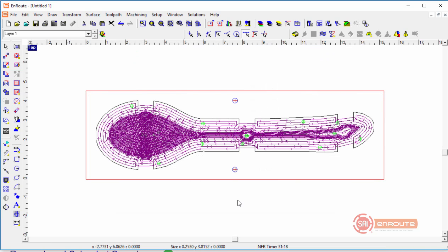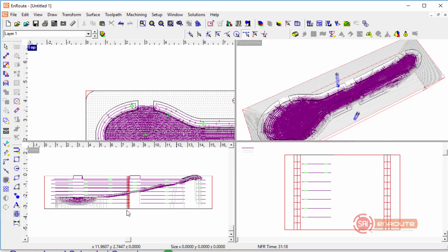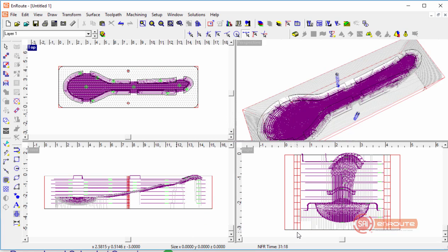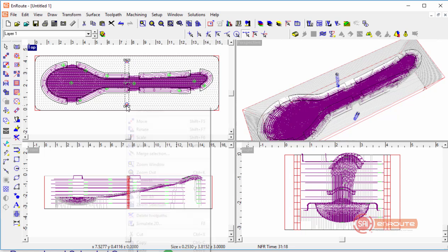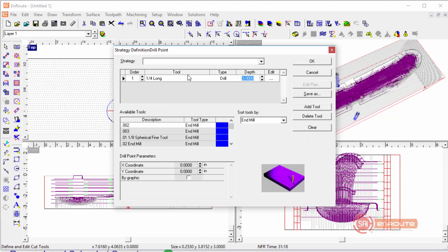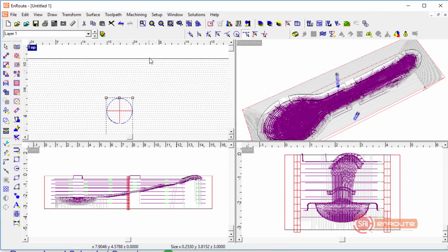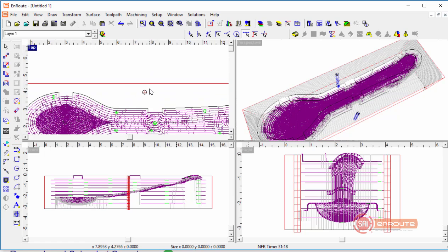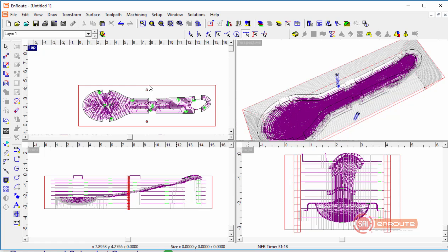All right, but there we've got a number of holes, and because of the depth of this one, we did it in a few passes to get all the way through to the bottom. And we actually, as we said, probably wanted to go here. Set up this tool path and go down just a little bit deeper so that you can place the dowel into the hole. And you can make your hole just a little bit bigger than that if you wanted to as well. That's just an example of a way to register the part, so when you flip the sides, side 1 and side 2 will match up. So this has been the completion of side 1 and the tool pathing for side 1. Now we're going to do side 2.